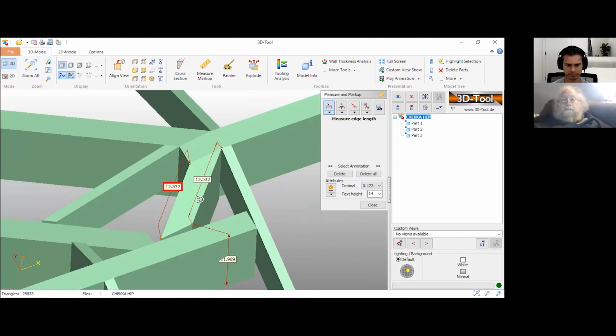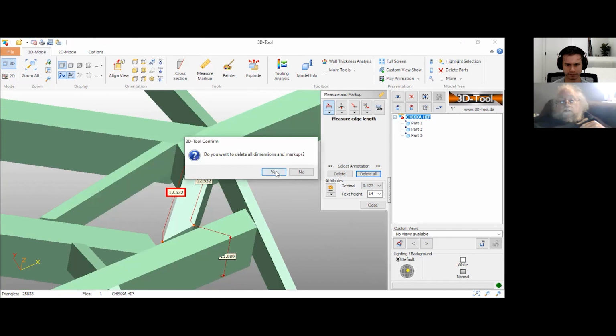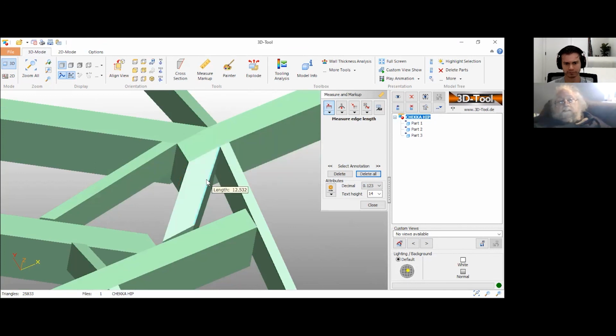And now, like I said, there's no reason why this little piece had to be 3.5 inches thick to carry that distance, but it's for convenience. It's so that you have something to bolt to. If you're going to run bolts through and bolt this hip through this ridge to that other little hip there, it's convenient. Or maybe they'll use those Simpson SDS screws to mount this.